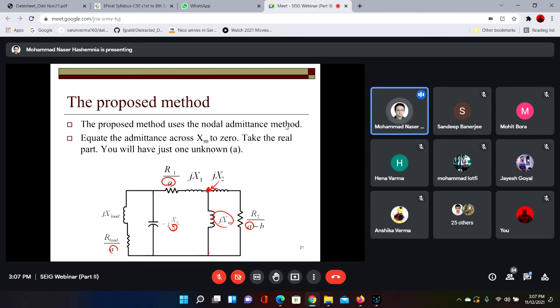So in my method, I first find A using the conductance across the air gap branch. Then if I found A, I can also obtain the value of Xm. I will explain it. If I want to explain more, you change the per unit frequency A in steps from below the per unit speed B to a value close to it.